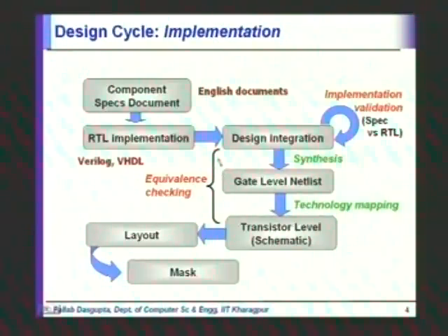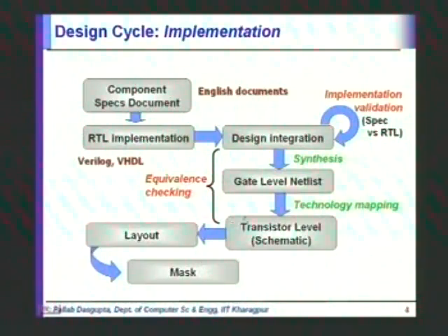All those are additional verification problems, in addition to making sure that the design has been correctly synthesized in terms of the functionality. By functionality I mean that whatever output you expect it to produce, whether it is producing that output. But timing means whether it is producing that output within the desired time. So that's a different thing altogether. And then after the transistor level design has been verified, then you go to layout, and then the mask generation takes place, which is the one which is fed into the fabrication machine.